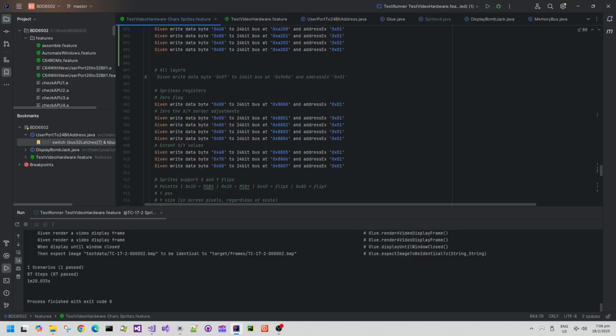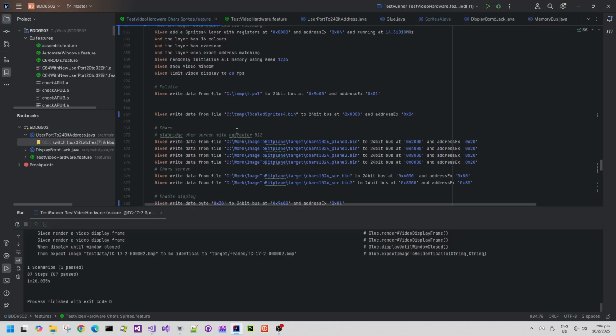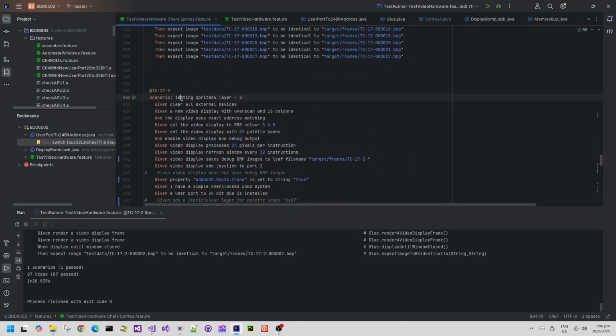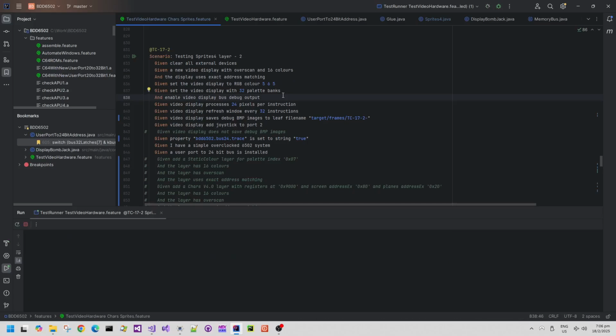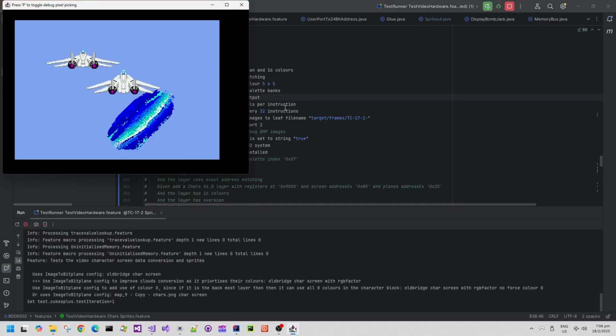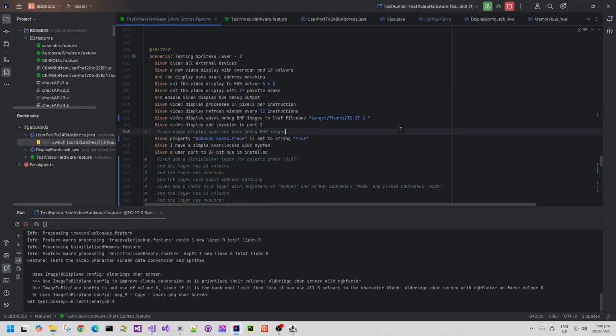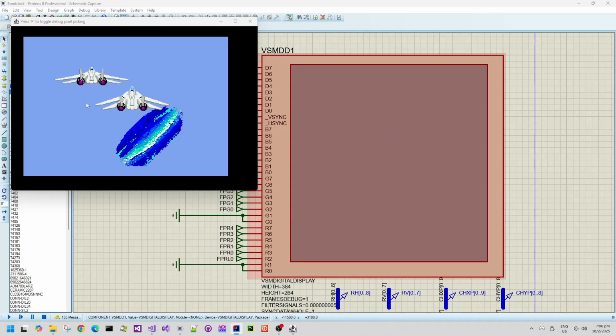The sprite register RAMs are also double buffered because while it is calculating and displaying sprites from the on-screen frame buffer, it allows the Commodore 64 to send data to the off-screen sprite RAM register list, compared to where the hardware is accessing the on-screen RAM.